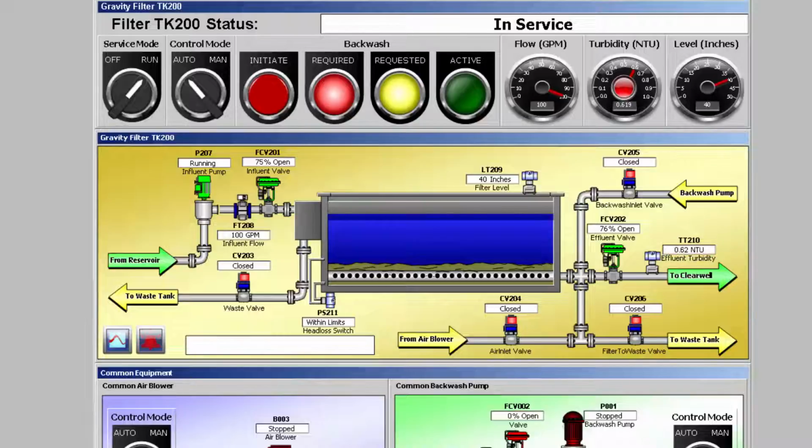I appear to have something blinking that indicates that I've got something in alarm, but there's an inconsistent use of color throughout the application. Not only that, this display is distracting. So if I very quickly needed to get to the bottom of a problem, or if something was trending towards a problem, would I be able to do that with traditional HMI graphics? So let's look at this same graphic with situational awareness graphics.